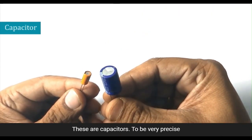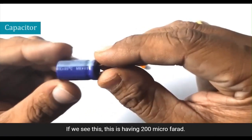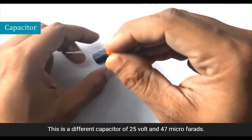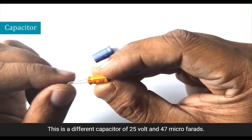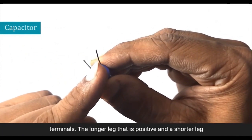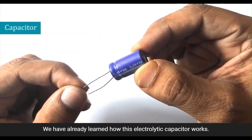These are capacitors. To be very precise, these are electrolytic capacitors with many different values. If we see, this one is a 200 microfarad 25 volt capacitor. This is a different capacitor of 25 volt and 47 microfarad. These are electrolytic capacitors because they have two different terminals: the longer leg is positive and the shorter leg is negative. We have already learned how this electrolytic capacitor works.